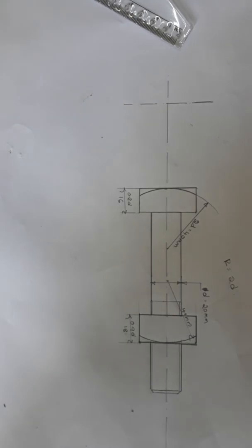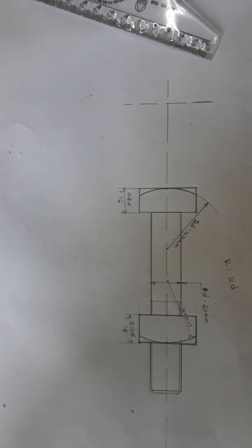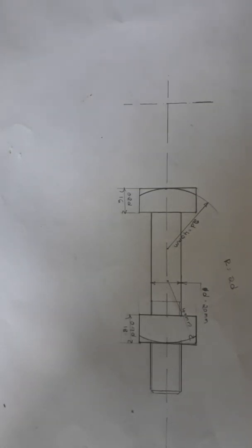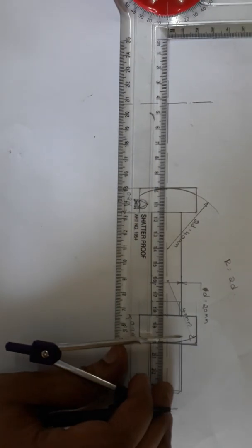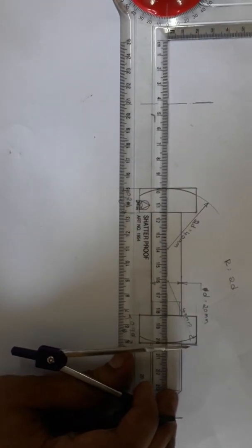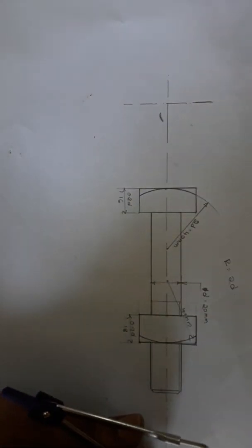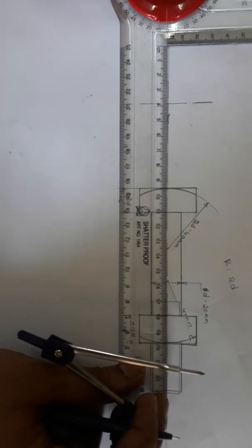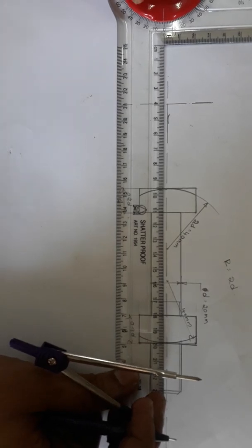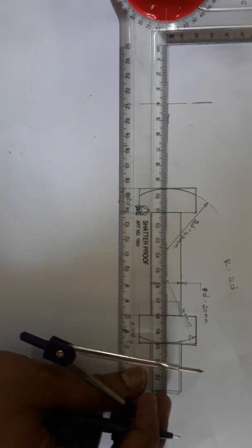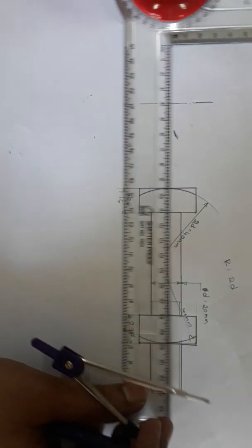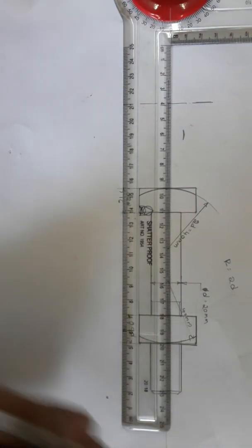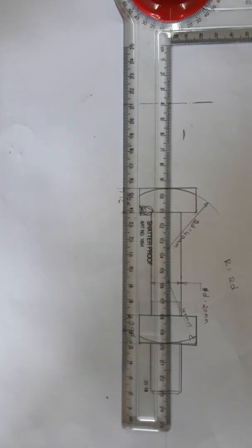This completes the front view of the square headed bolts with a view across flat. Now you will draw the side view of this. For drawing the side view, match the center line. Whenever a drafter gets offset to draw the angle lines, you have to match with your axis lines so that you will get straight projections. That is a very important point to remember, otherwise if it varies, the projection will vary. Keep that in mind.